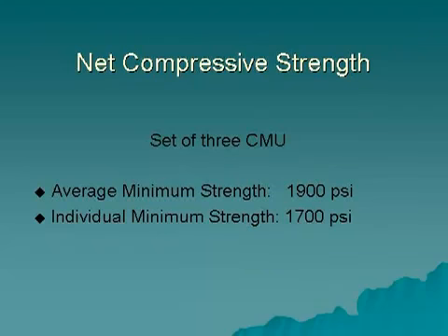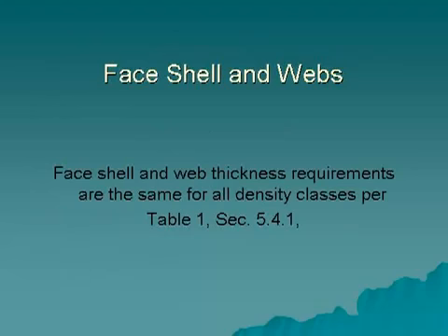All concrete masonry block, regardless of concrete density, must meet the same minimum concrete strengths and geometrical allowances. Higher strengths can be specified if required for design, but typically must be ordered well in advance of the date needed to ensure curing and strength attainment. A premium is usually charged for higher strength block. Check with the block supplier regarding additional cost relating to high strength block. Face shell and web thickness requirements are the same for all concrete density classes. In other words, lightweight block is not required to have thicker face shells or thicker webs to be load-bearing.